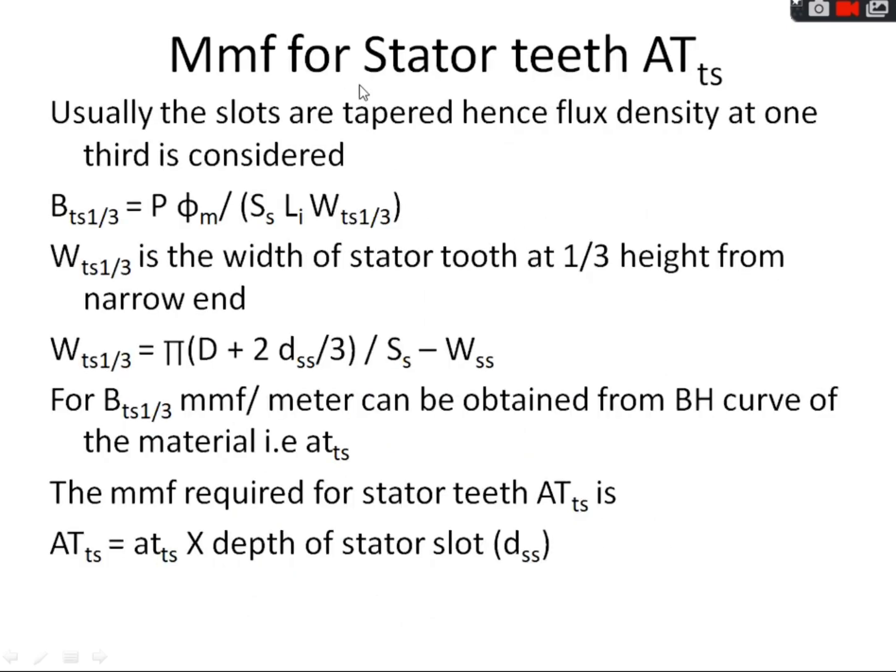Next is the magnetomotive force required for the stator teeth, that is given by ATs. Usually the slots in the three-phase induction motor are tapered. Hence the flux density throughout the teeth does not remain the same. So what we do is we take into consideration the flux density at 1/3 the width of the stator tooth, that is 1/3 of the height from the narrow end.